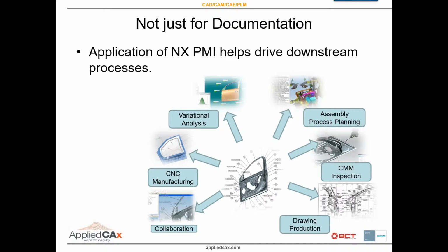If you're using NX PMI, it's not just to make the design engineer's life a little bit easier. You can consume that information in downstream processes: assembly process planning, CMM inspection, and CNC programming, where the programming time is much reduced. And if you place 3D PMI on your part, you can then pull it into your drawing if you need to create a 2D drawing.